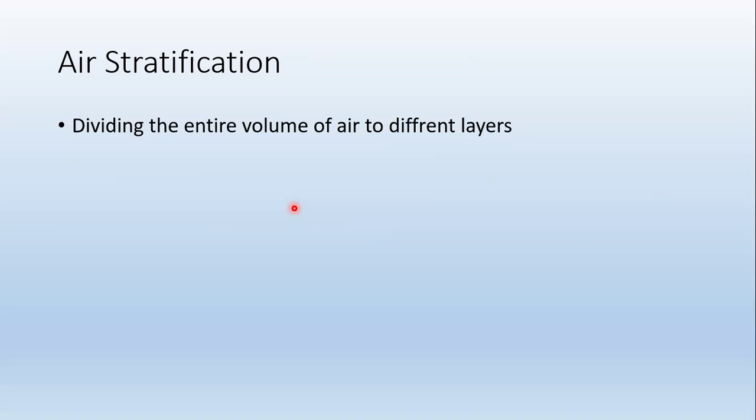Why? Because from those diffusers, you will be getting the cold air. Now, we studied that cold air will always have high density. So eventually, it will come to the bottom side of that area itself. And that's how the entire area is getting cooled down. At the same time, the hot air will always prefer to go upside. So this is meant to be the air stratification itself.